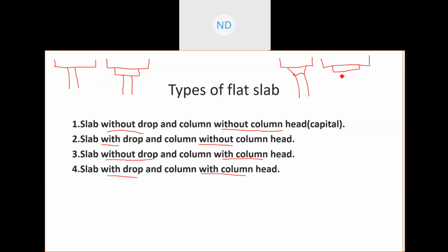So you have a drop panel, you also have a column head, then there is a column. That means in this fourth type, the slab is resting on the drop panel as well as the column head, and finally on the columns, distributing its loads.